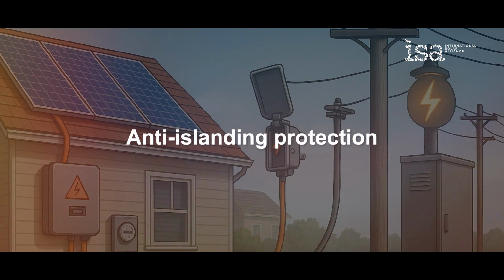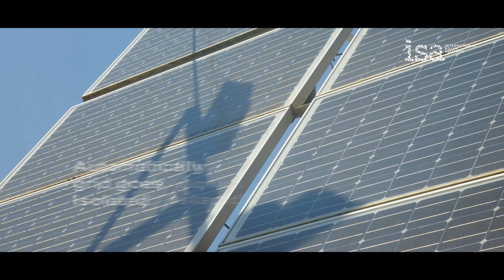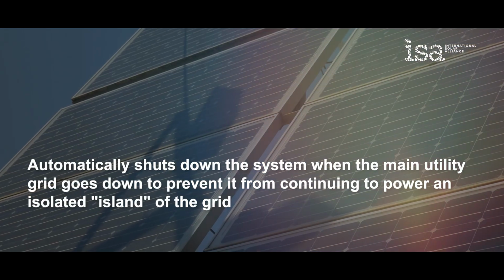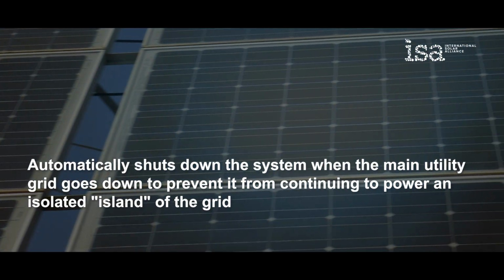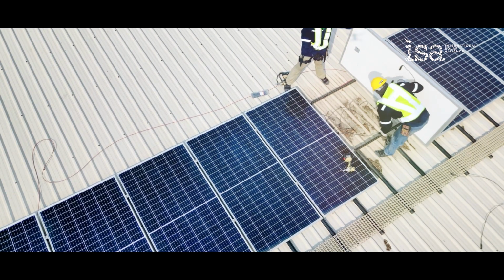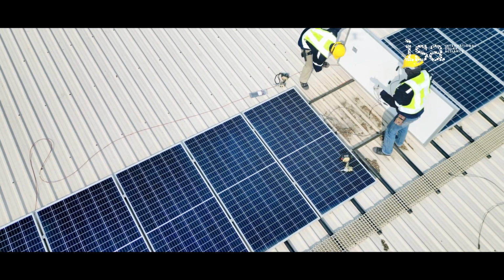Anti-islanding protection is a safety feature in grid-tied distributed energy systems like solar that automatically shuts down the system when the main utility grid goes down to prevent it from continuing to power an isolated island of the grid. This is crucial for protecting utility workers from electrocution and preventing damage to grid equipment during power outages.